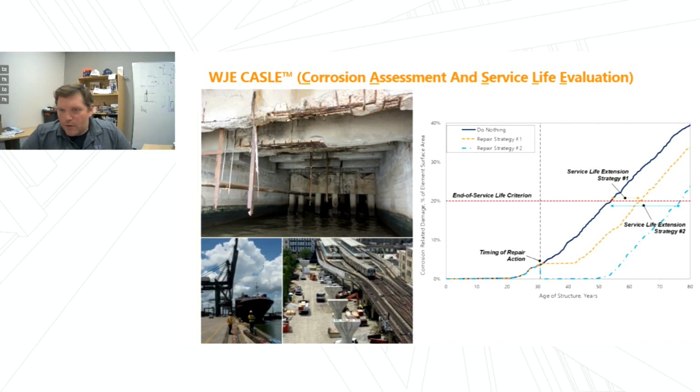Ultimately, as part of all of this, we're taking this data and we're doing asset management. And chloride testing is a small part of that, but it's important to understand the chloride diffusion behavior as well as the construction in order to do appropriate service life modeling and asset management.